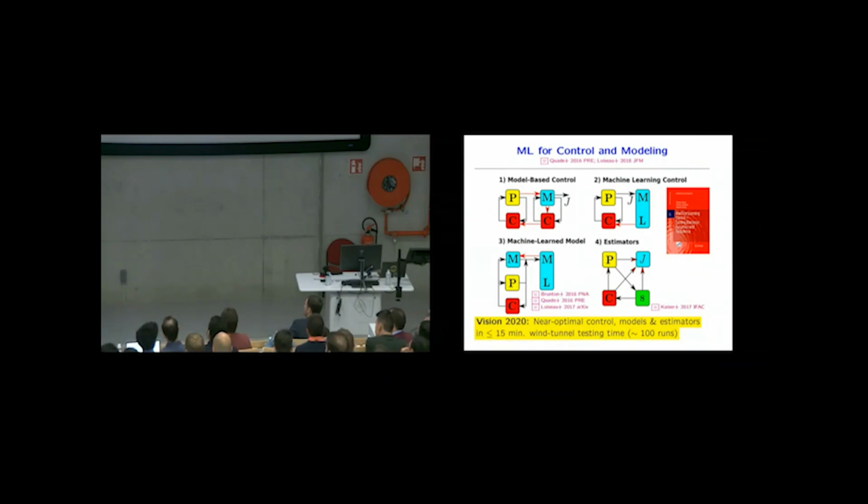So we're doing this with Wolfgang Schröder for the turbulent boundary layer, but we can also extend the ridge line to controllers. So this is a new concept. And the interesting thing is that the ridge line tells you if you have an easy play or a hard play. If you do the ridge line and figure out you always go inside your data domain, then you are screwed. You can only improve things by an order epsilon. But if you go to the fringe of your domain, like we have seen here, then you know what you need to do. So in case of the actuator, increase the frequency and decrease the duty cycle. So the machine tools give you hints.